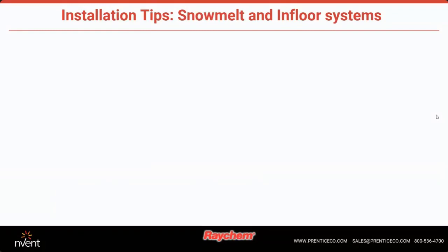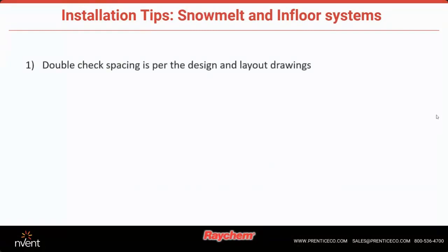All right, installation tips for snow melting and in-floor systems. So with snow melting and in-floor, every project is different. You know, the layout and the spacing for the cables can vary greatly. So please don't go based off of an installation manual only. Go based off of the actual project design, or if there were layout drawings provided, go based off of those.